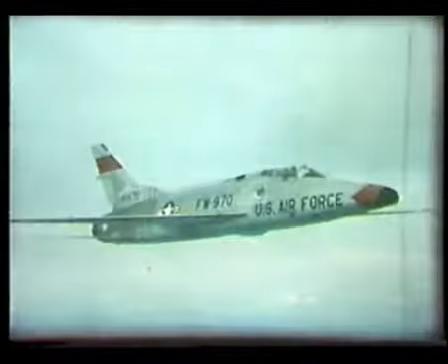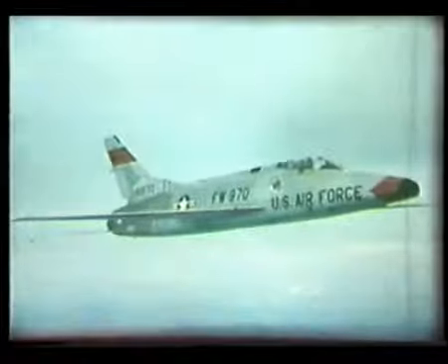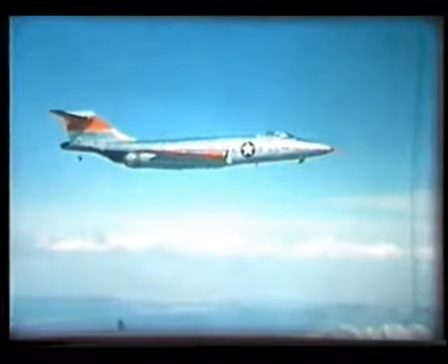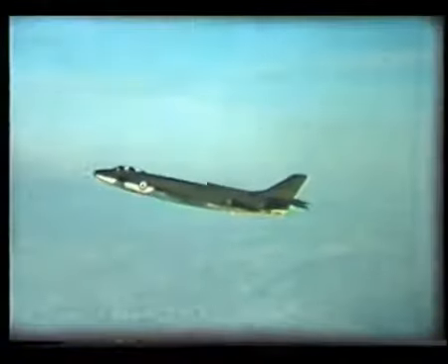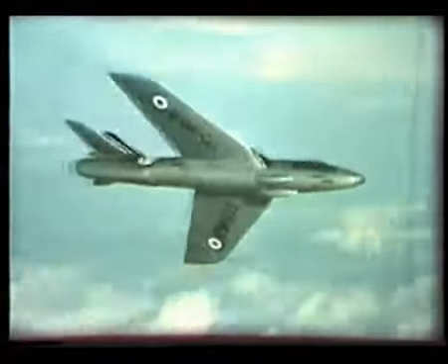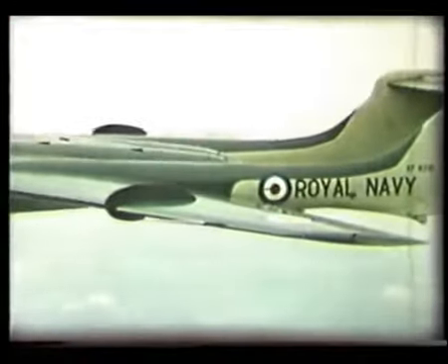Above Mach 1, the bow wave adds its own drag. This can be reduced by having leading edges, nose, sharp rather than rounded. Compare the effect on the bow wave of sharp and rounded leading edges. In these ways, designers are gradually solving the problems of transonic flight and building aircraft that are safe at high and low speeds.